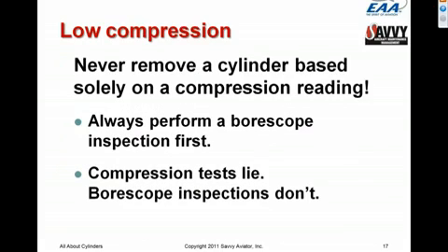There are a few things that can cause an engine not to put out full power. Worn cam lobe, seriously incorrect timing on the ignition, stuff like that. But wear in the cylinders just doesn't do that.